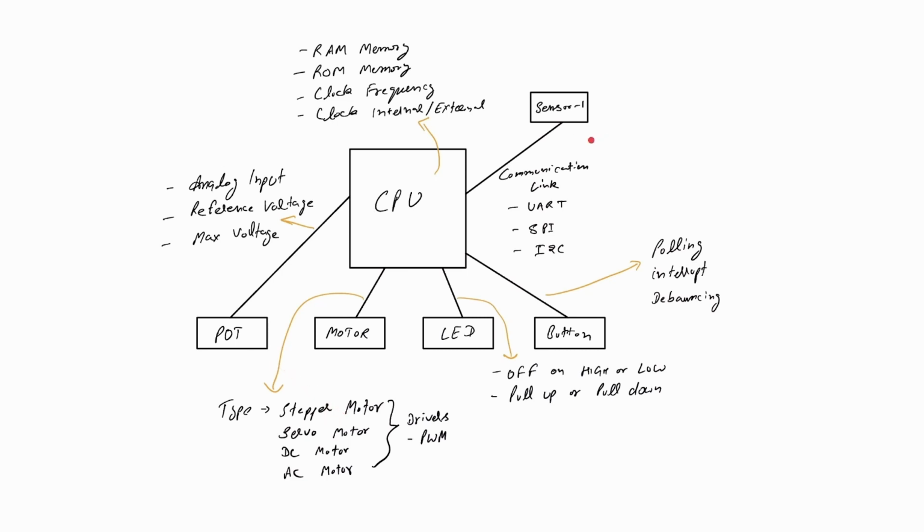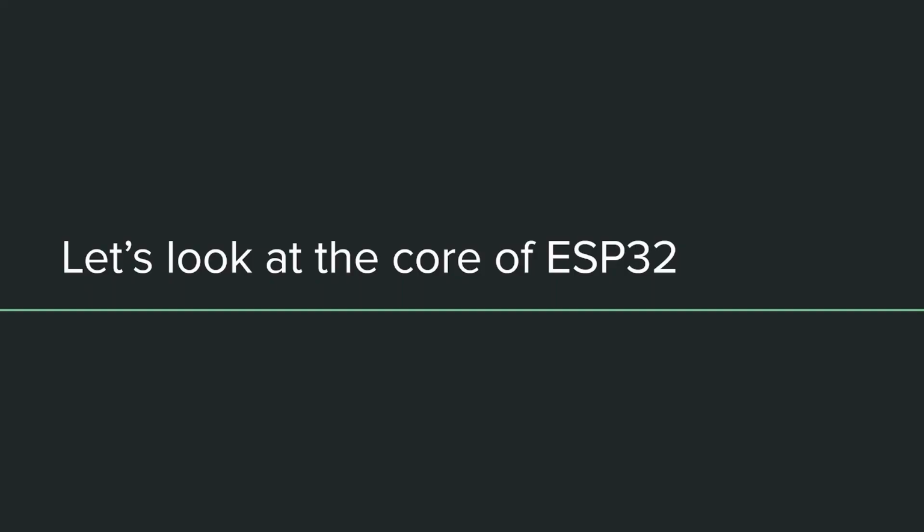Sensors, as we previously discussed, you should be able to read the IDs. Not all the sensors are going to have an ID, but you find the ID on most of the sensor chips as well. But you can hook up an oscilloscope or a debugger to find out if your sensor is working or not. Let's look at the core of the ESP32.